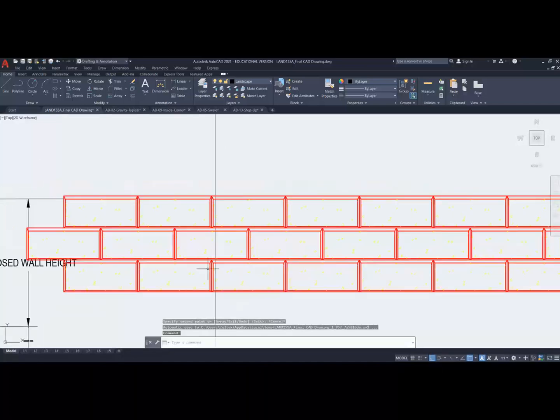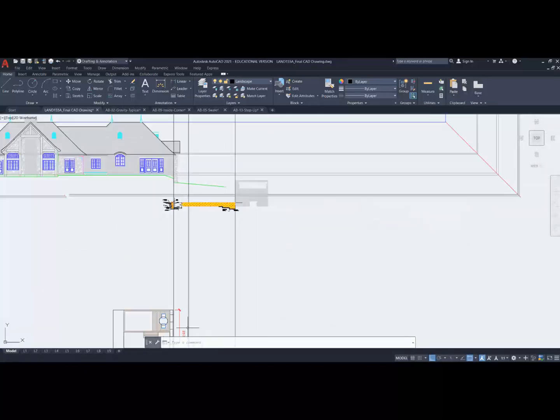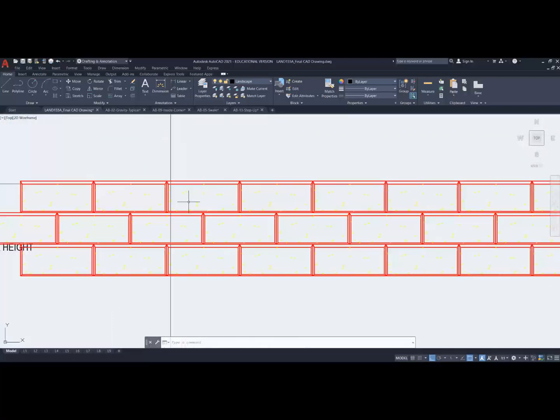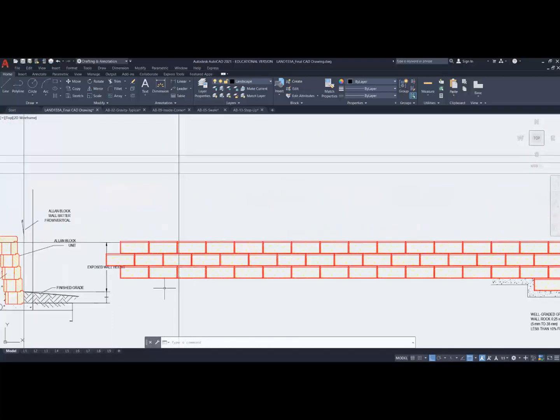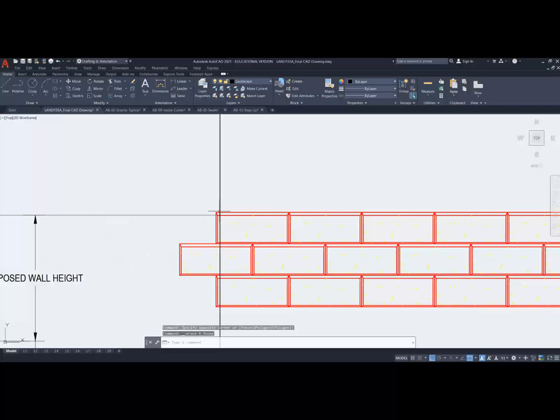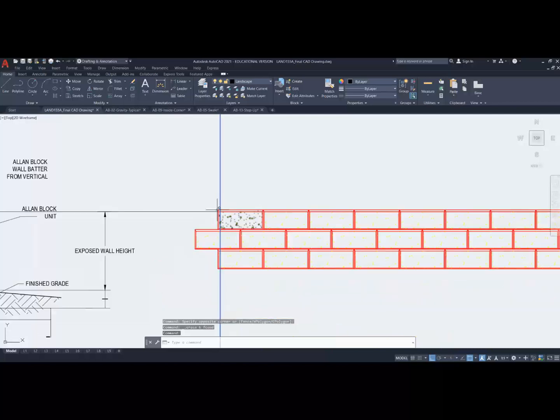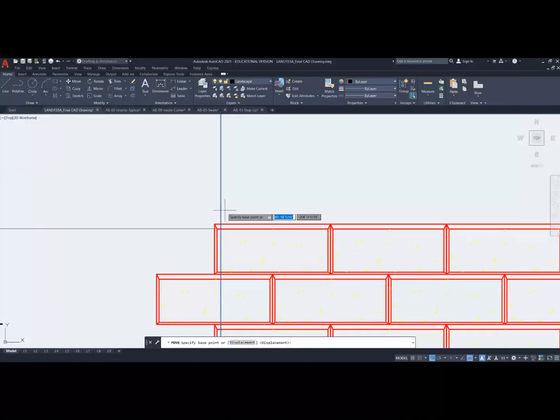I don't want to have to do extra cutting. See how this 23 foot 3 inch distance doesn't work out properly? That's where I need to take what I've got here and now decide, hey, am I going to adjust that length? Yes, I am. So I want to make sure I'm on a full block here. So I'm going to move that. And remember, anything you adjust here in terms of its length, you should adjust in the plan view as well, because you're going to base some of those measurements from there. And I will move this edge so I get a nice full-size block here.